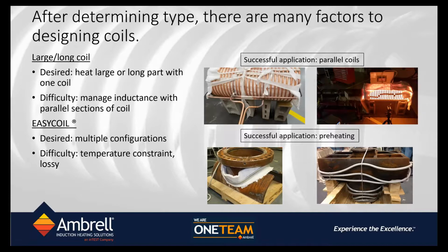This is where the experience helps, because a simpler coil is easy to make, it's easy to maintain, and if the coil is damaged, it's easy to reproduce. So even though the shapes and the sizes of the coils can be very intricate and complex, the goal should always be to design the simplest possible shape that can do the job.